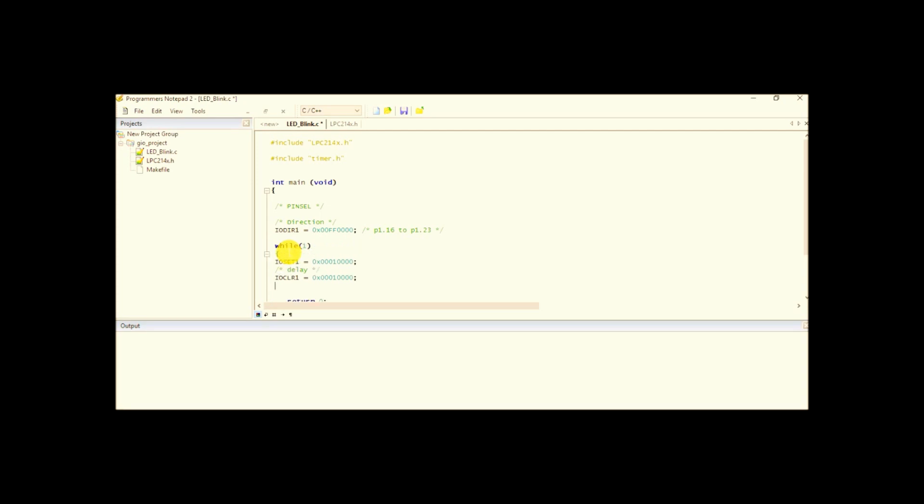In embedded systems, in all the embedded systems, it's always a while loop. That means the board is supposed to do this repetitively. It should not exit this main code. There are some scenarios, like if you are going to sleep or restart the system, where you may exit this loop, but in general, once the system starts, it should not leave this loop.